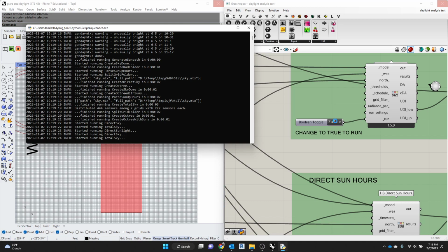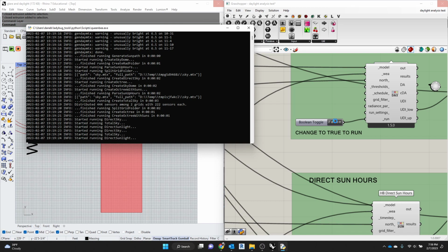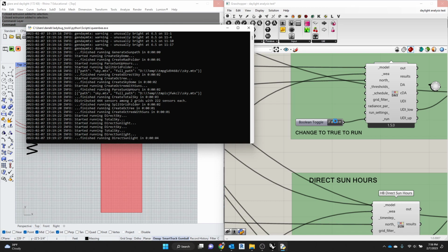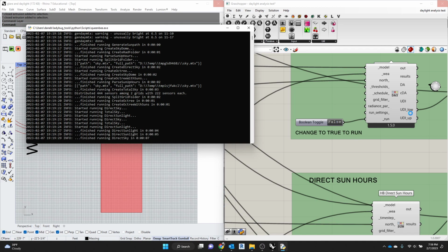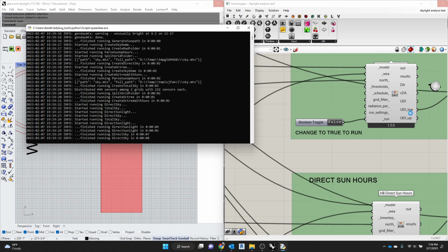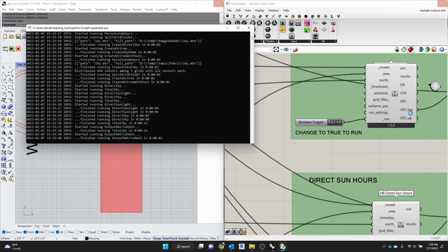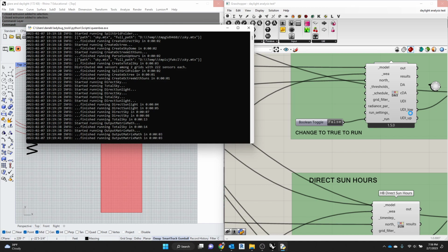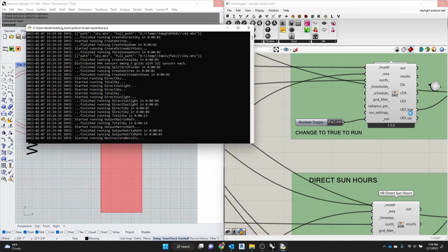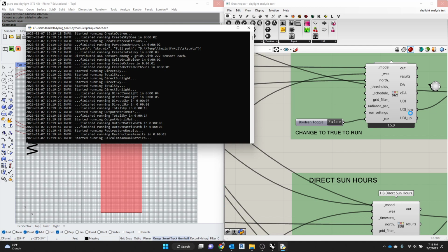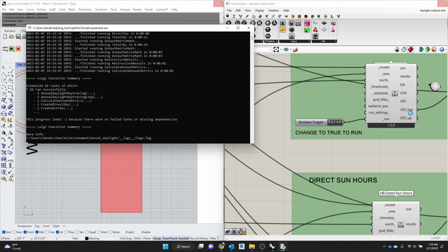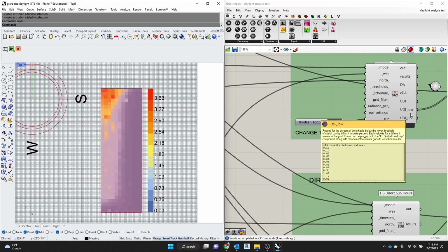It's going to run. It's going to give us a slightly... So right now I have plugged in the low. So what do we think this is useful daylight lower. What this is actually going to show me is what percentage of the year am I below the threshold in spots. So at every spot in this room, what percentage of the year is it below the level of light that I want it to be?